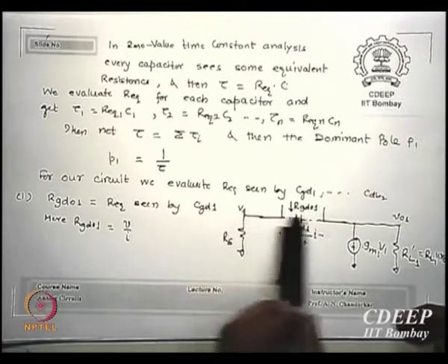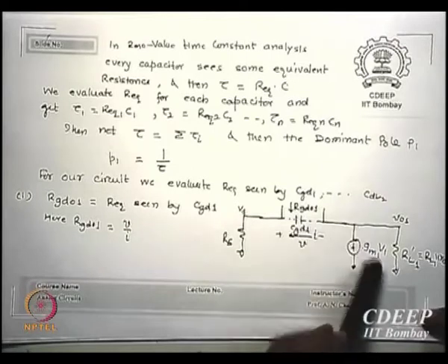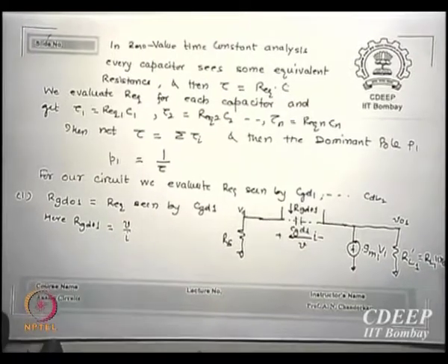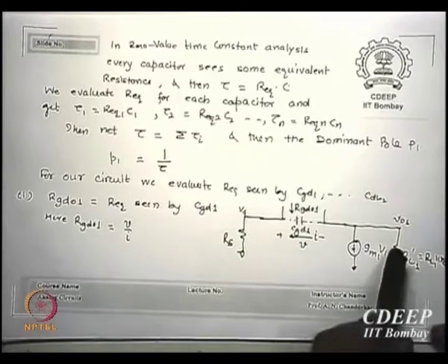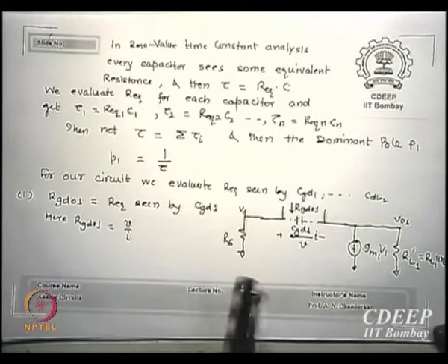Then there is a CGD1, a capacitance here, and at the output gm V1 plus RL dash. Now we assume that the next stage is removed, as if its equivalent input is shorted. So we say the output is VO1, where RL1 dash is RL1 in parallel with RC. If your RL is high, you can say RL dash is RL1, that is fair enough.